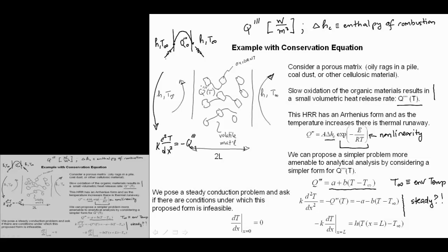So what that says is, if I increase the thickness of this, and I had the exact same amount of generation, the temperatures inside have to increase because the integrated amount of power inside has increased. I haven't changed the surface area. So to get a steady state, to make sure that I get the heat out of it, the peak temperatures have to be higher.